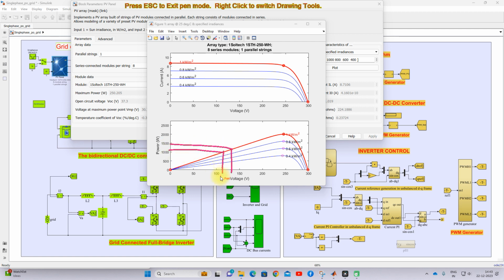Consider this the current instant and this the previous instant. You have to take the difference between the current instant value and the previous instant value. Here you will see that the current voltage is less than the previous instant, so you take the subtraction Ci minus Pi, and the voltage sign will be negative. Here also the current instant is lower than the previous one, so Ci minus Pi gives a negative sign. This is known as del P and this is known as del V. The sign of both del P and del V is negative.